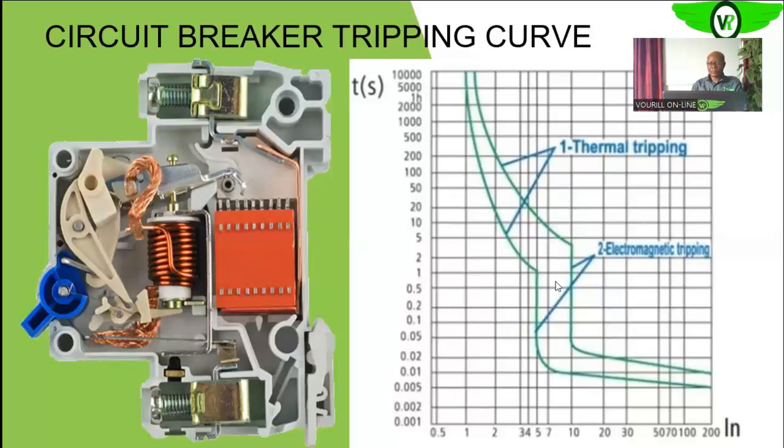So you should always know this, so that when you are either coordinating your circuit breaker or selecting a circuit breaker for your particular circuitry, you need to also know the ambience of the working environment. So that will make you have a better informed choice. So that is what we have on this graph.